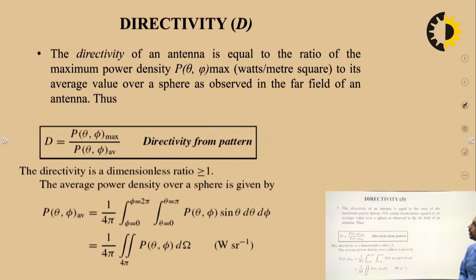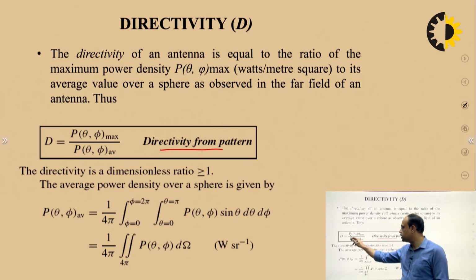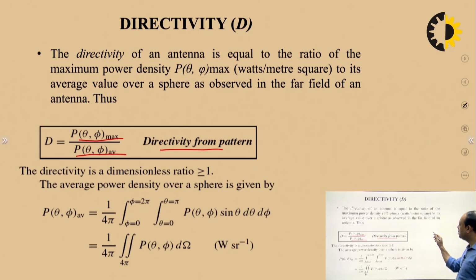Directivity, this is one of the important things in the case of antenna transmission. Directivity is nothing but the maximum power transmitted over the average value of the power. Like if we have an isotropic antenna that is radiating in all directions, and it transmits a power P, while if that same amount of power is directed by a directive antenna in a particular direction, then the ratio of this distance over this distance is known as the directivity of the antenna.